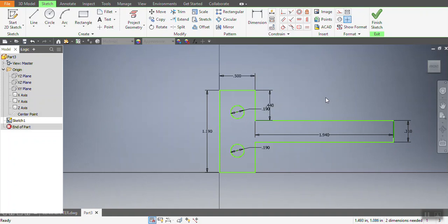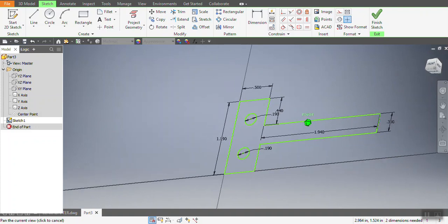I'm going to finish the sketch. I'm going to save this work, and then I'm going to extrude it. Okay? That's the order of things. And when you want to see how it is really extruding, that's why you want to bend your view a little bit using the view cube on the top right-hand corner. So move the view cube a little bit at an angle like this so that you can see the three-dimensional extrusion happening in front of your eyes.